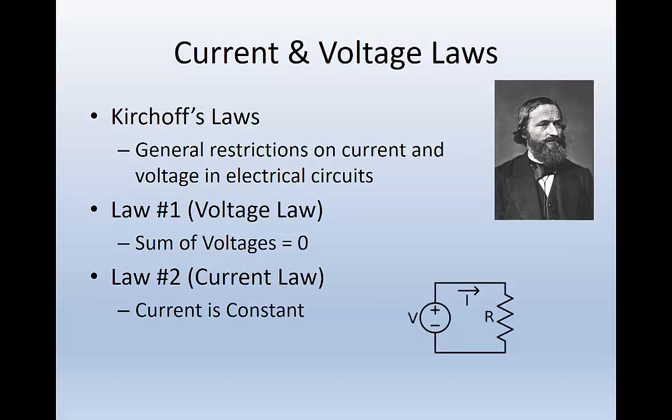All right. So let's talk about those circuits for just a second again. Within those circuits, we have some different laws we're going to use, and these are by Kirchhoff. The first one is, and when we talk about this, we're talking about in series. First off, we know that the sum of the voltages is equal to 0, meaning that if I add up the voltage across any set of utilization equipment, maybe there's one here, and one here, this plus this will equal the voltage here at the source.